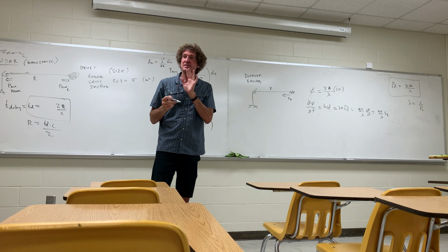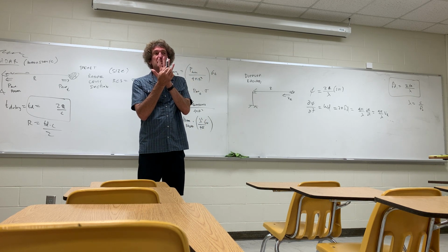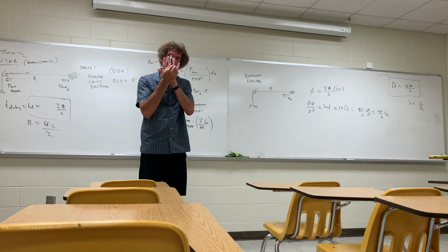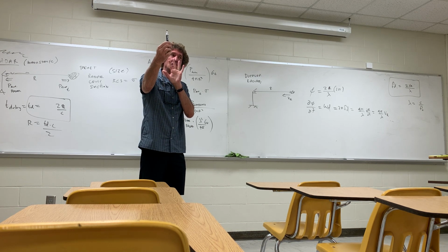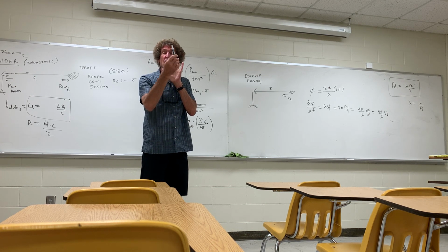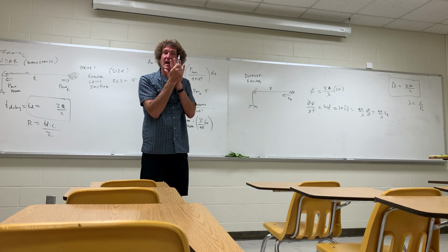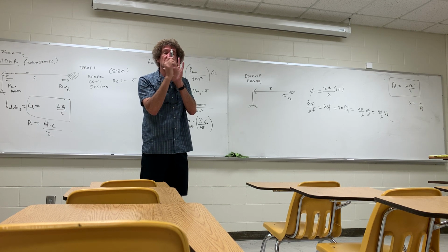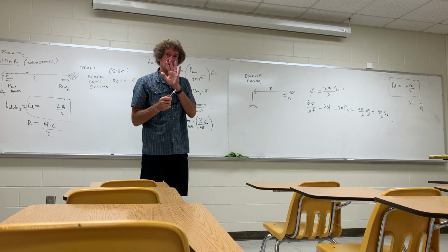So if I sent a signal at 1 gigahertz, say it's a radar signal that has a carrier frequency of 1 gigahertz, I send it, it hits a target. When it returns, if the target's moving towards it, it will have slightly greater frequency. It would be the transmitting frequency of 1 gigahertz plus the Doppler shift. If it's moving away, it would be the transmitting frequency minus the Doppler shift. You follow me on that, guys?